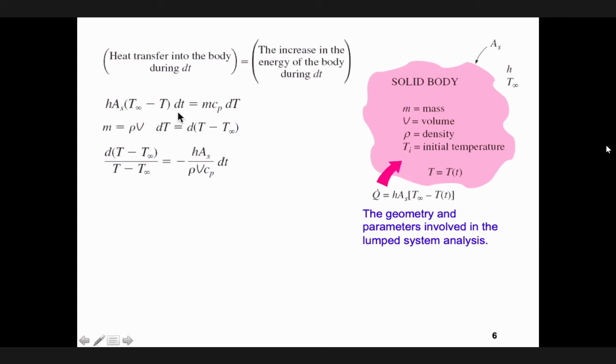Again, here is the variation of the temperature that you have, dT. Again, we are changing the variable because, I hope you feel comfortable here, dT and here is the same, because if I take the derivative of this expression here, this is the variable, remaining dT, and this is constant. The derivative of the constant is equal to 0. Therefore, we are using a change of variable. By assuming this dT here is this one, my equation will end up like this: h times the area divided by rho Cp. Therefore, this is the differential equation. I just changed it to this format.